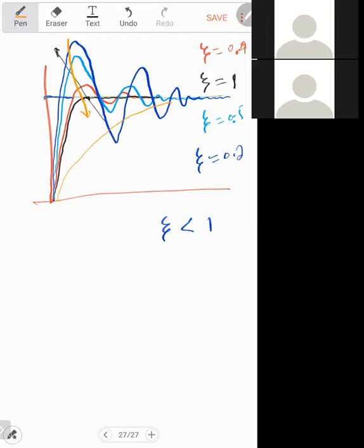The two poles will lie on the same point, and the system will smoothly come into the steady state position and nicely rise. If zeta is increased from 1, and you increase it further, the system response will become slow. So that was the conclusion.